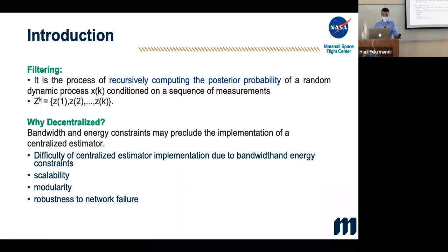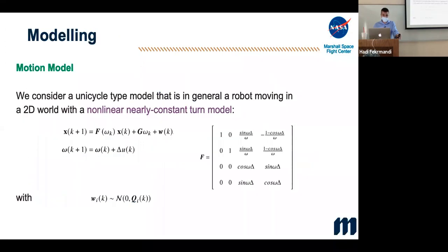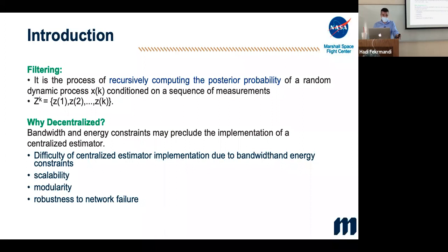I am moving, and at the same time I'm making measurements. There's a prediction of where I'm going based on the transition model of the robot, and at the same time I also make measurements simultaneously. Filtering allows us to combine this data, prediction and measurement, and get a better estimation and reduce the uncertainty, which we show with these ellipsoids showing the uncertainty covariance.